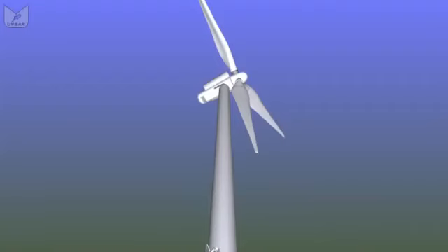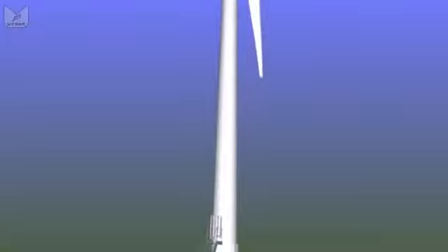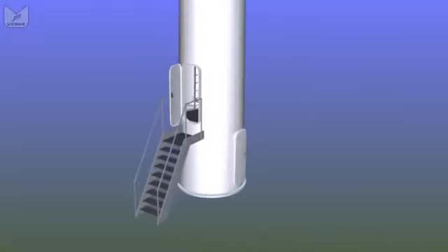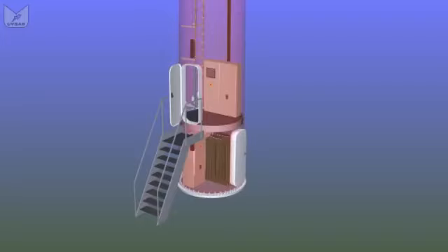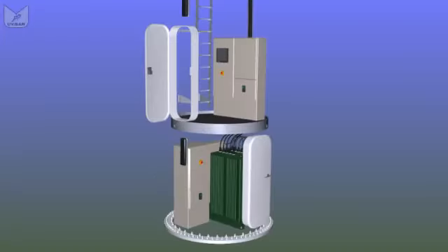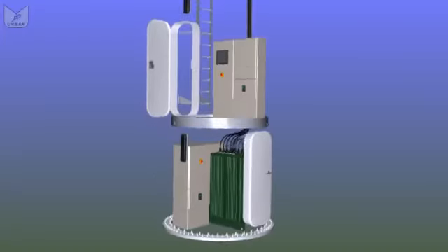Turbines of this type are typically 25 to 45 metres tall, and at the base you will often find 2 doors. The lower door takes you into a secured compartment where we have a high voltage step-up transformer. The generator at the top of the turbine is producing about 690 volts, and this transformer converts that into several thousand volts to send it more efficiently to the substation. The main entrance to the turbine is at first floor level, and there we find the control cabinet and the base of a ladder, or a series of ladders.